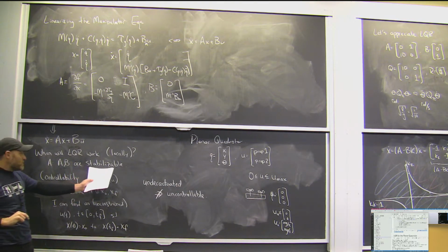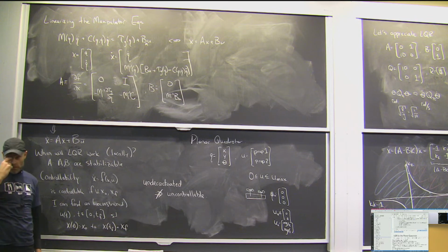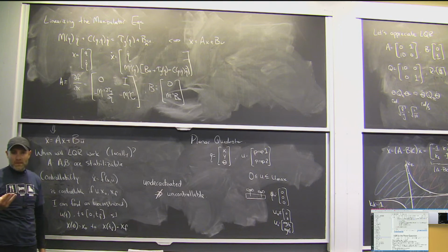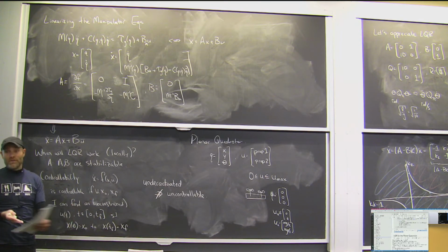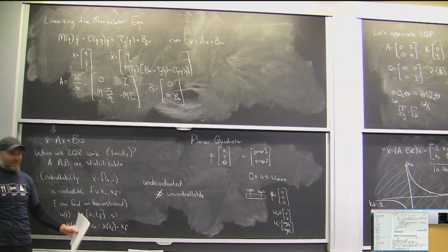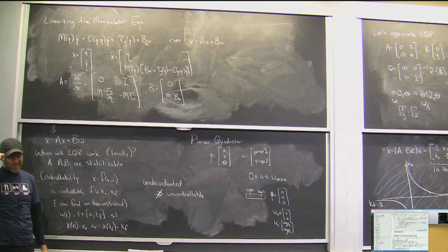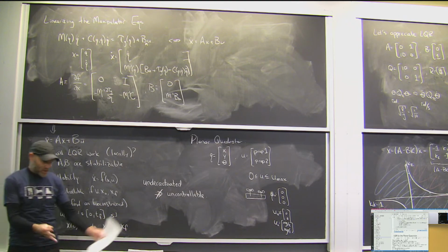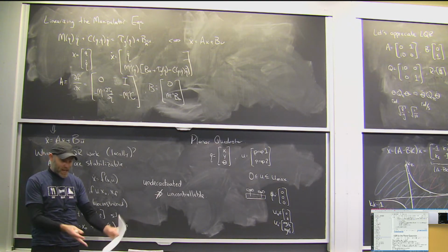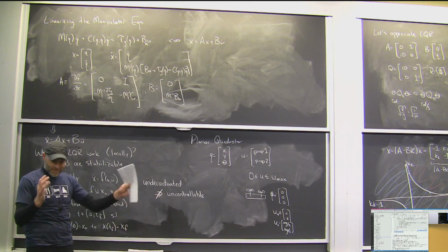If you care, stabilizable is a slightly weaker form of controllable, because if you have a system that's already stable, it's okay if you can't control the directions that are already stable. So if I had a system with no actuators, but it was stable, then that's still stabilizable, I guess. Maybe that's a weird limiting case. But let's say I had one actuator, like a pendulum over there that was controllable, and a bunch of other things here that were stable, not connected to that.